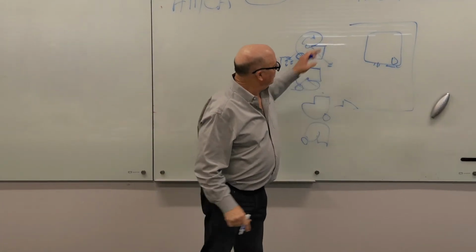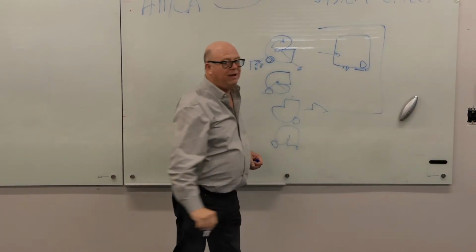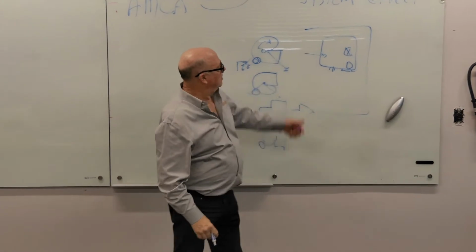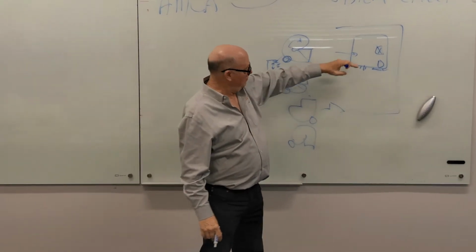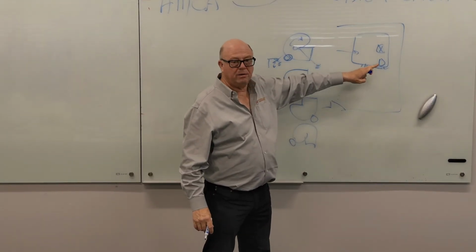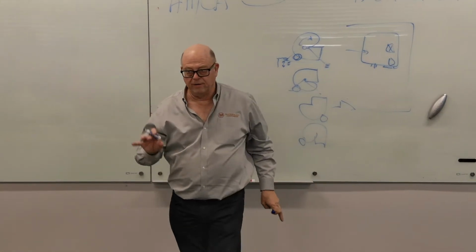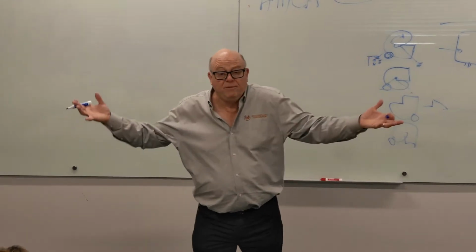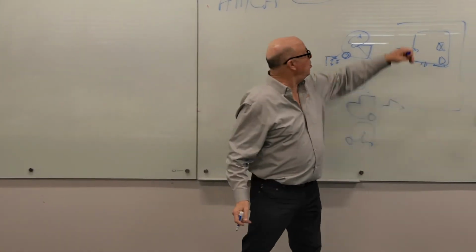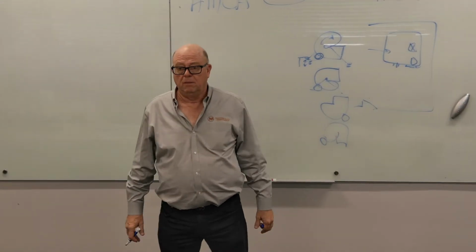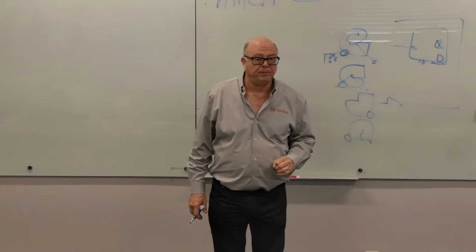Okay, the air's coming this way and maybe it's going out the top. If this is a Carrier, that's a right-hand motor and a right-hand coil. Because for an air handling unit, you have to specify both, and they don't have to be the same. You might have a reason why you want the coil on one end and the motor on another end. But you have to specify both, okay?